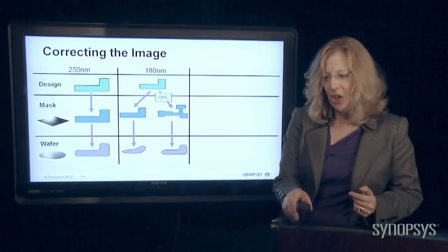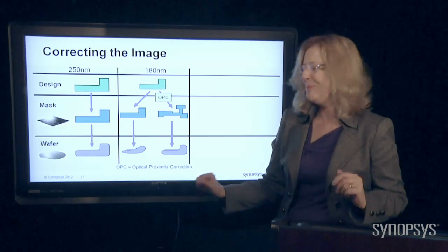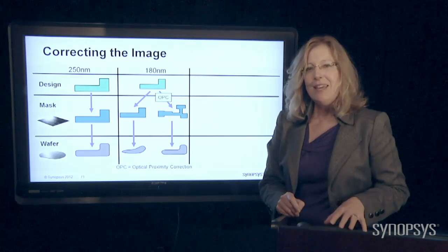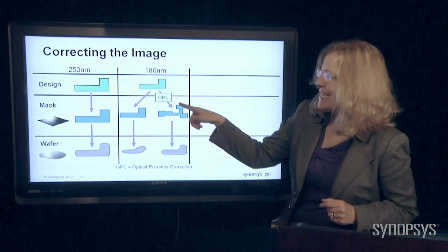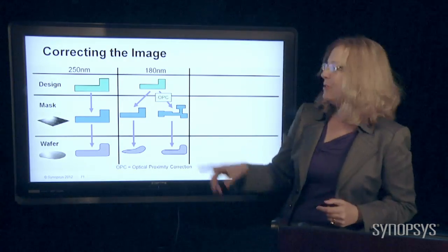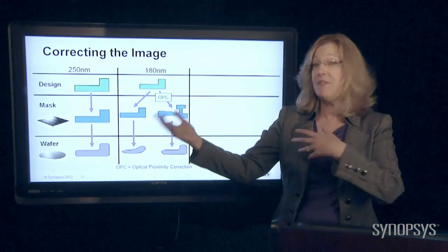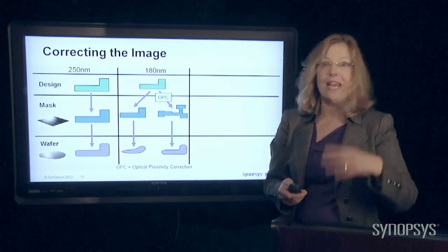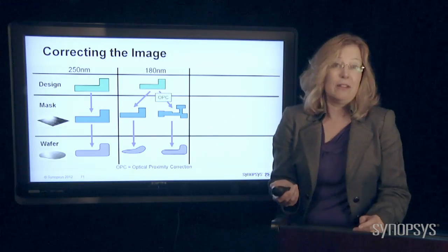This step is called OPC, which is officially optical proximity correction. And these little extra rectangles that get added on, they're officially called Mickey Mouse ears. But you can see the technology now in just a software tool has been able to say that light's too big, trick it, now I can get exactly what I want, and I don't have to go buy an entire new manufacturing process that includes X-rays or some exotic thing like that. Okay, so life is good again for a few more years.